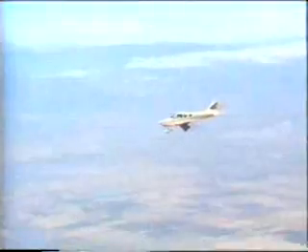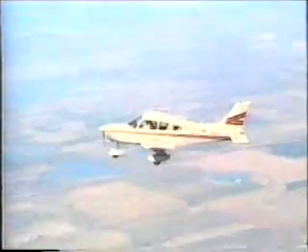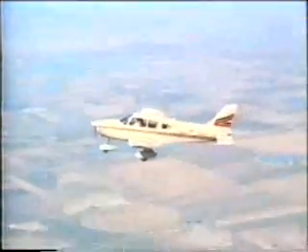If you don't apply additional thrust or it is not available and the critical angle of attack is exceeded, the airplane stalls, regardless of weight. An example of this is an airplane at full power. As additional weight is added, the only way to increase the coefficient of lift is to increase the angle of attack. In an attempt to maintain steady flight as weight continues to increase, you'll eventually exceed the critical angle of attack at a full power setting.